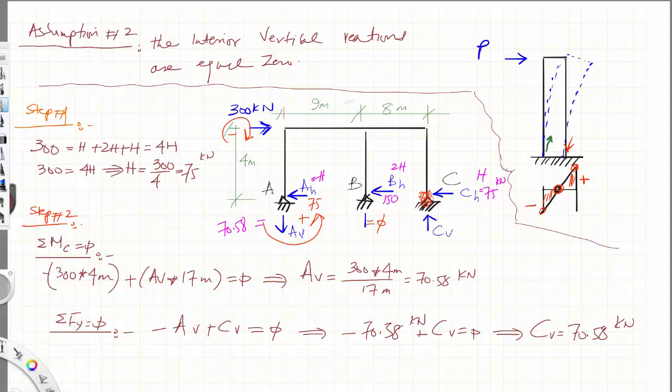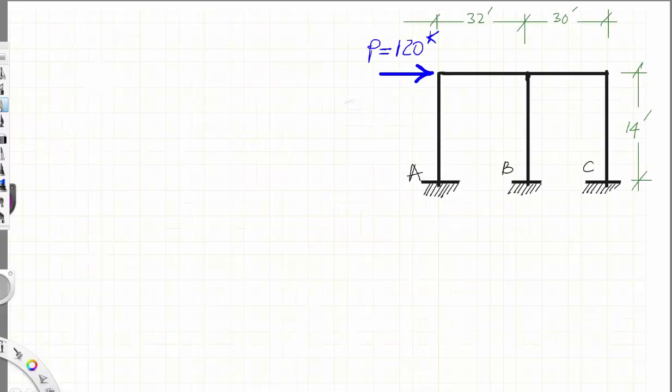Okay, so far we have done all of these frames, and if you have noticed, all of these supports were hinge, and that is not the case normally with buildings. The supports are fixed. So let's do an example of fixed, and in this case, besides the reactions, assume this reaction is downwards, and this is of course upwards, and of course these are horizontal ones.